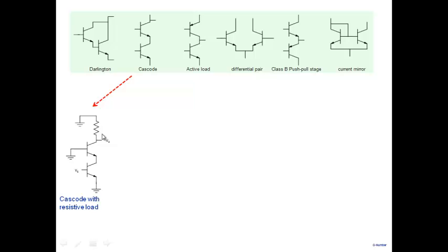Now, one of the ways of generating new solutions is to combine various existing solutions, solutions to different problems. So I can take this cascode, and if I want to build really high gain, then I know that I should take this resistance out and substitute it by an active load, right? So I could do that. This is my drive transistor, cascode, and the active load is used over here. All right, so I can get this particular amplifier configuration. This will give us much higher gain compared to this one, and I won't suffer that much in terms of frequency degradation because Miller's effect is minimized here.